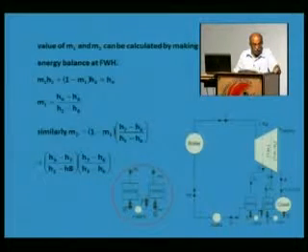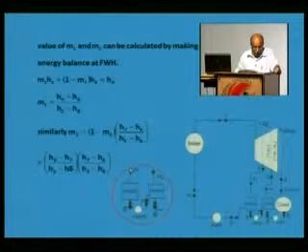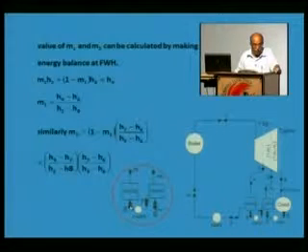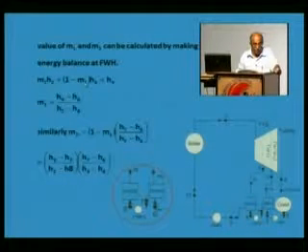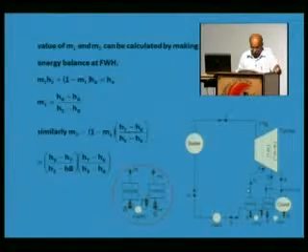Say feed water heater here, m1 H2. In this case feed water heater 2, this is the m1 quantity of steam entering the feed water, and the quantity of water coming here is 1 minus m1 at 0.8. So, the total energy coming to the feed water heater is m1 H2 plus (1 minus m1) into H8, and that is equal to H9 here. Make an energy balance for this feed water heater. The total heat coming in is equal to total heat going out, and that gives us m1 equal to this.